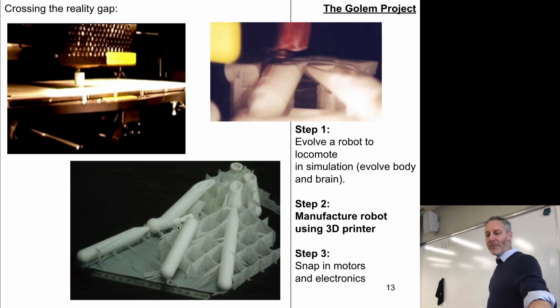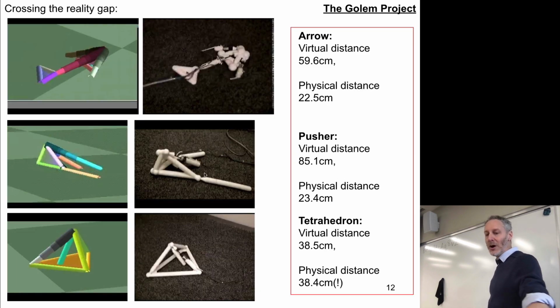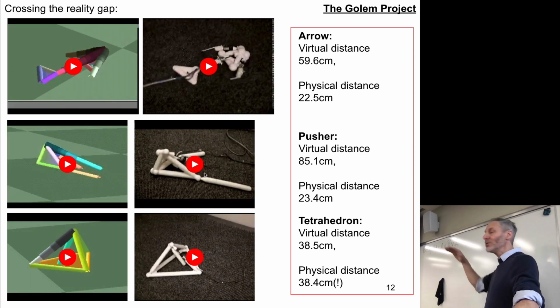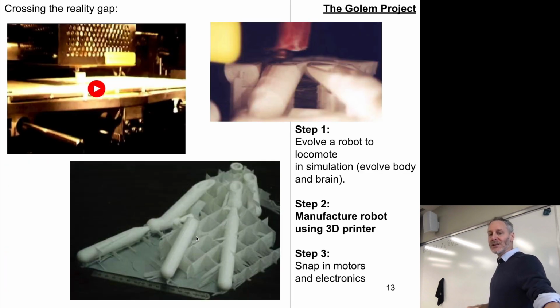But depending on the 3D geometry of the thing you want to build, building it in 2D layers is difficult. So these early 3D printers and a lot of 3D printers today print additional stuff. This is just weak scaffolding to literally hold up the parts that are being built. It took about 8 hours to print each of these robots.